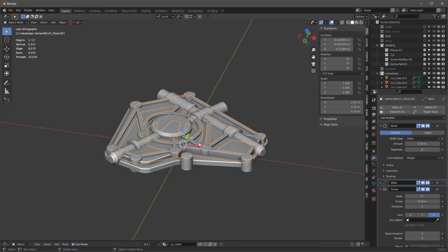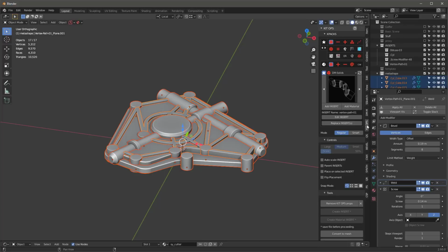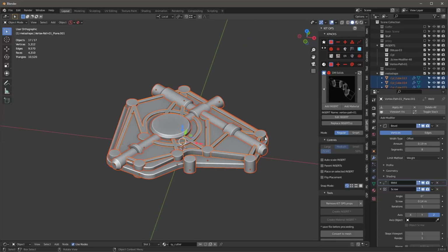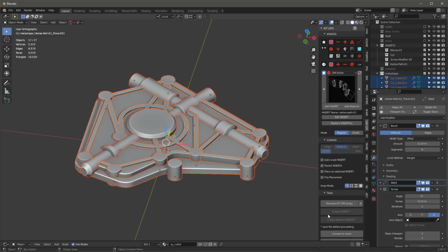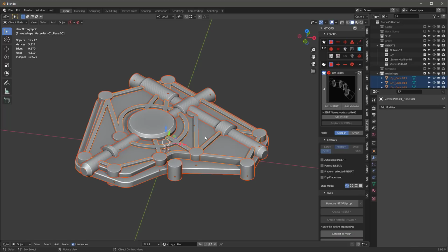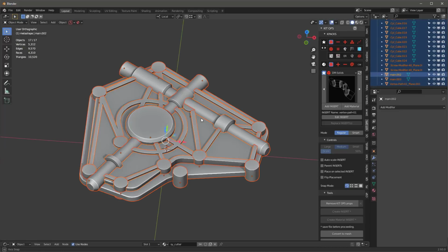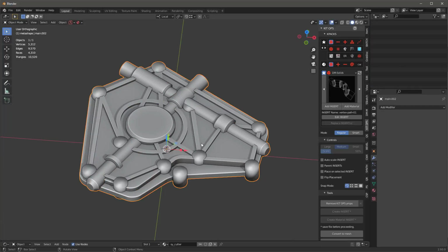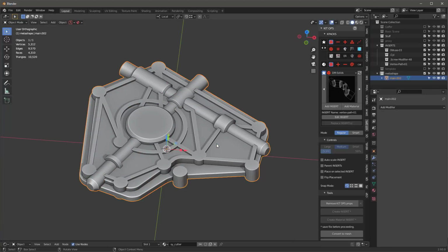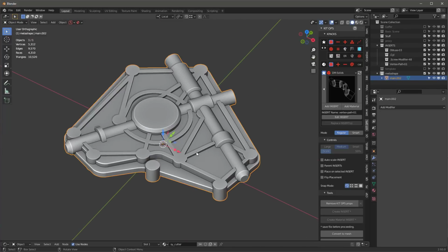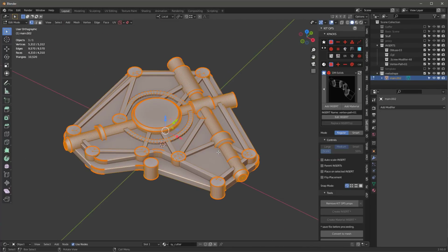With metashape, I'm going to select everything and go into KitOps. I use KitOps for this because I want to convert things to mesh, and KitOps has some special code that always gets it right. Not all of the ways to convert objects to mesh get them right. KitOps will. So I'm going to look at this and say, yeah, that looks pretty good. Let's convert everything to mesh. Now that they're all converted, I want to shift click on the main one, right? So if I look over here, main is selected, and I'm going to say Control J, which joins everything, and then I'm going to shade flat everything. So now we have this, which is one solid mesh.